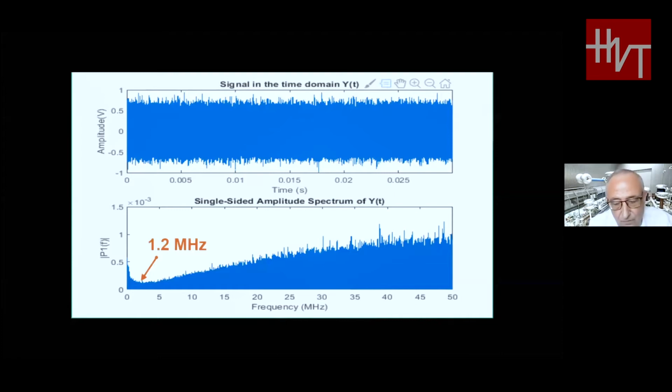The wavelet transform, blue box technology, removes the modulated noise automatically, but maintains pulse noises, because a priori you don't know if a pulse is a partial discharge pulse or an electronic pulse due to electronic noise. For that reason, the second step is to use clustering techniques in order to identify the cloud that corresponds only to the noise. These are two different kinds of noise.